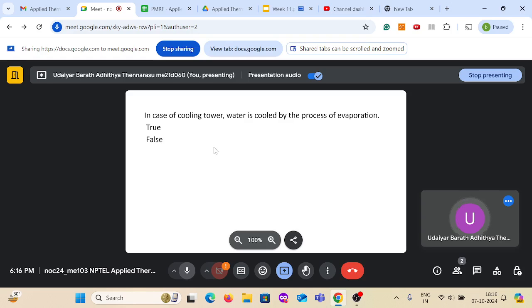Because the air is not saturated, it needs some water. It can accommodate water till it reaches saturation. The water takes energy from the water droplet itself to convert to vapor, so the water droplet temperature will go down and some amount of water will convert to vapor and go with the air.